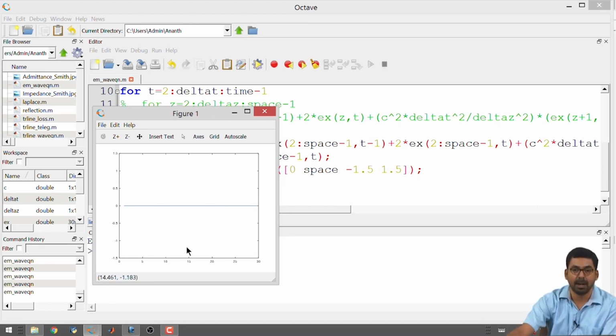You can assume this to be some kind of an open loop control system, where you have an incoming signal and you have a box which has a transfer function, and then it has an output on the other side. You want the input to pass through to the output and not come back, so that you can determine the transfer function H by taking output divided by input. So, you want to make sure that it happens only once. In most of the simulations, at least you make sure that the wave does not travel back, unless the study itself is aimed at figuring out what happens when the waves travel back explicitly. So, this is known as absorbing boundary condition, and it can be done in multiple dimensions, which we will see later.